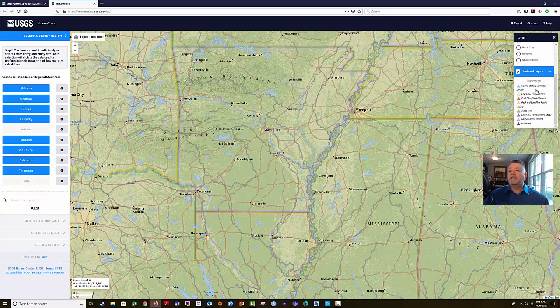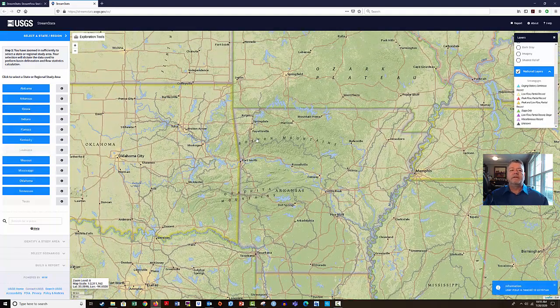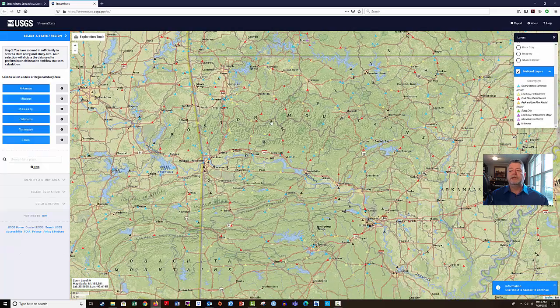So here's the key for stream gauges. Continuous are blue, low flow or peak are yellow and red, and orange, low flow and peak. Partial, stage only. So we have this set of keys. We're not zoomed in far enough to actually tell. In fact, right now we have to have regional curves based upon which state we're working in, and it's asking us to select a state. Well, don't select that yet till you zoom in. It'll reduce most of those options for you.